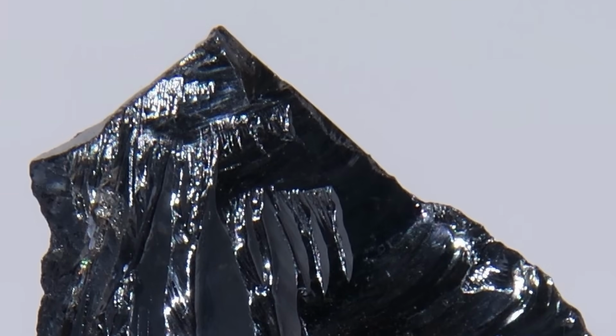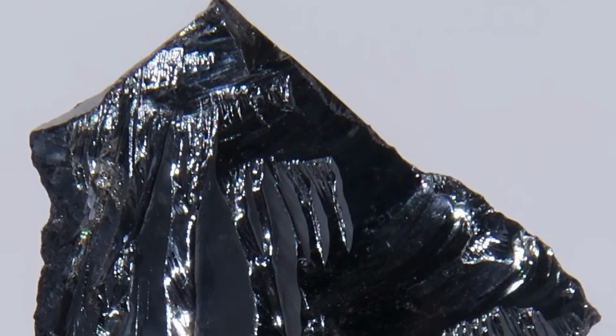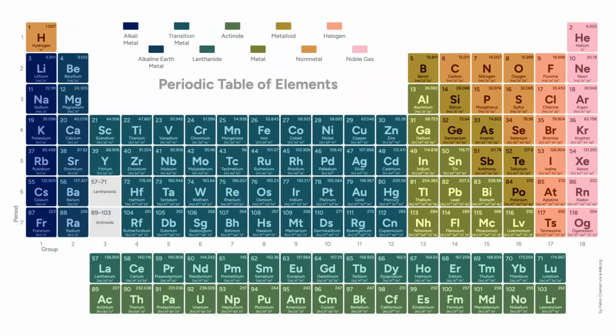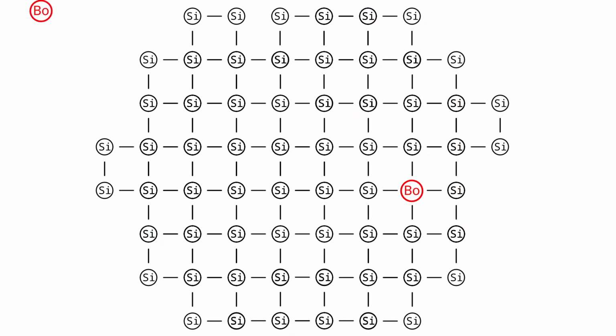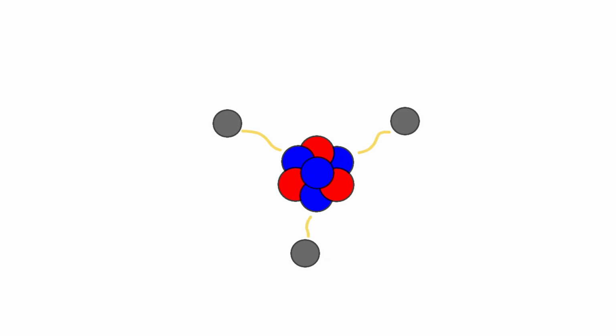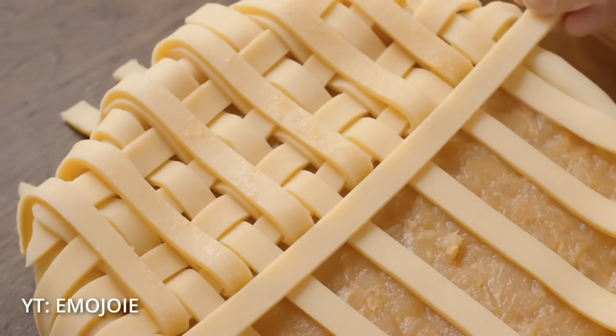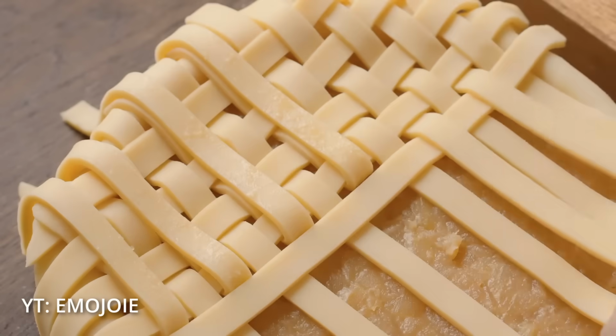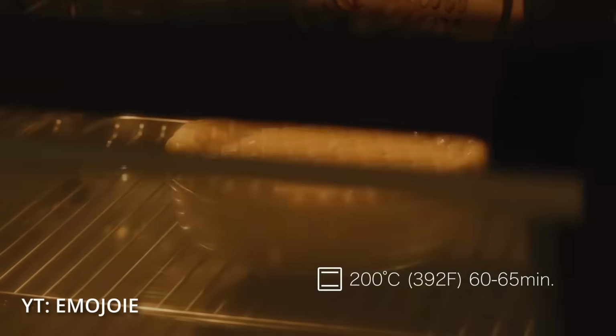So a semiconductor material is a material that's actually a pretty poor conductor. And if you use it just as it is, like a chunk of silicon, germanium, or selenium, or gallium, it doesn't really do much. You have to dope this piece of semiconductor material with an impurity. Now, there's a whole lot going on here with valence bonds and tough physics, and I'm not gonna go that low, because we're just chasing down this. If you wanna make an apple pie from scratch, you must first invent the universe. But essentially, when you dope your semiconductor material, you're choosing very specific impurities to inject into it to give that semiconductor material an imbalance in one way or another.